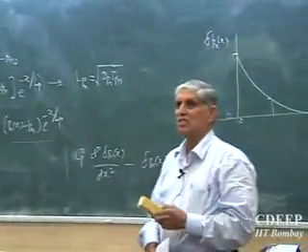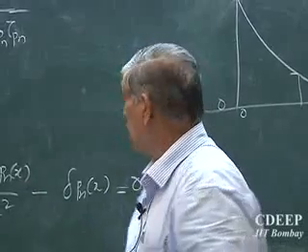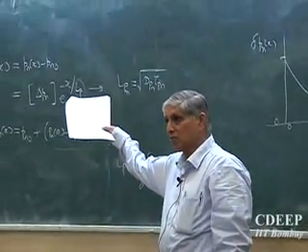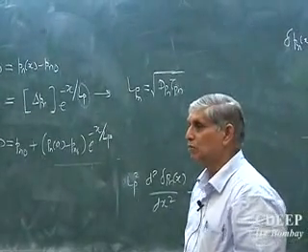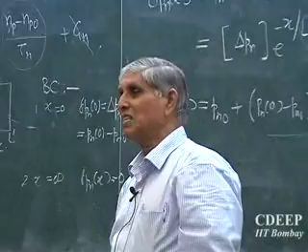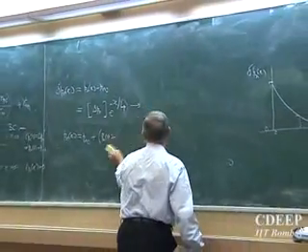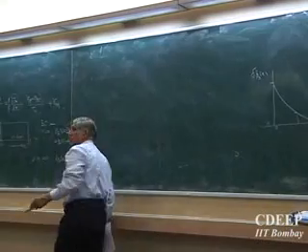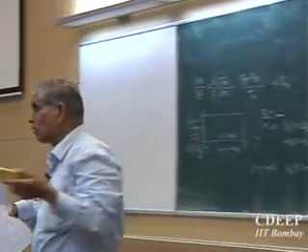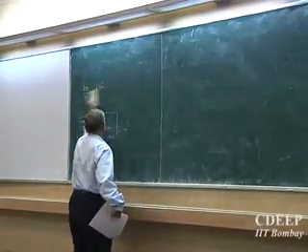So this issue has to be understood by you, that this excess carrier concentration decay relates time and space to some extent, at least in steady state. We say dN by dt is 0. If not, then you have to solve this full partial differential equation. The left side is a time-dependent term, so I must somehow convert that into a term which is relatively easily explainable, what is dN by dt, and then solve the equation numerically, which is possible some other day. In our case, we will assume I apply a voltage and I will not remove it. If I apply and remove, yes, there is a transient case which will have to be solved. What happens if a transient occurs? As far as steady state is concerned, this is good enough.